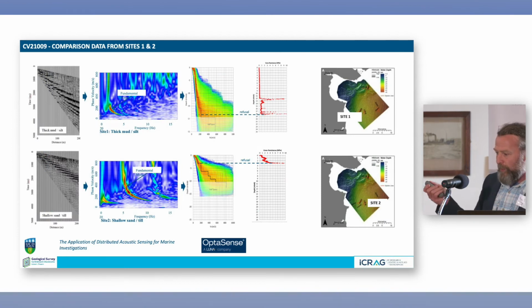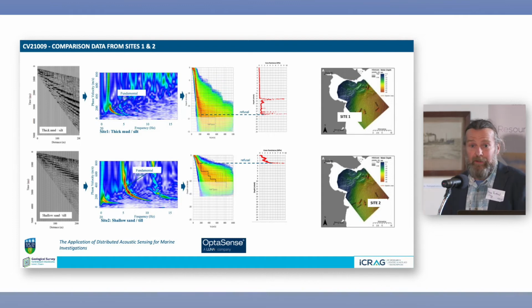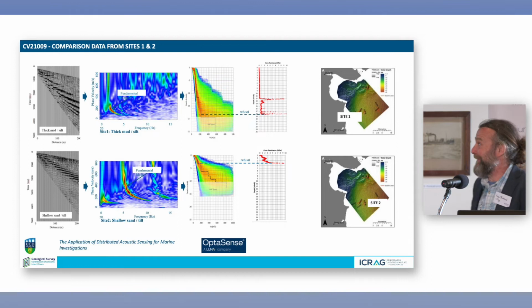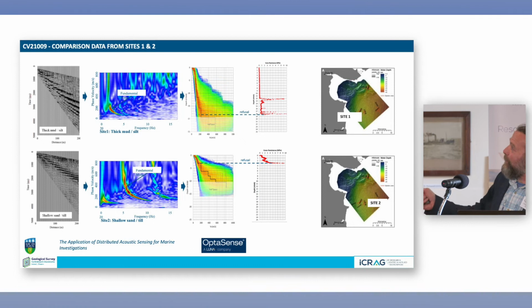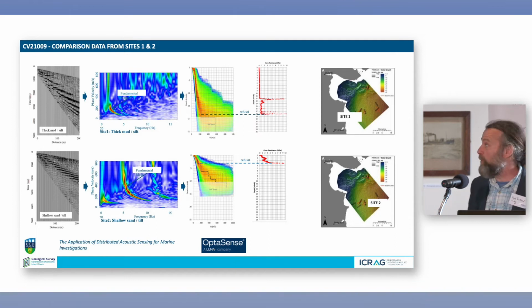We did work on different geological settings, so you can see that we get different characters of these. And again, this to me is incredibly interesting, probably to 90% of you it doesn't mean anything, it's not really exciting, but I could talk about this slide for weeks. But basically, we have a thick mud site on the top and we have a till site on the bottom. This signal here is the mud, and this is what we get from the till. And basically it's just to illustrate that we can map different subsurface properties using the surface wave method.